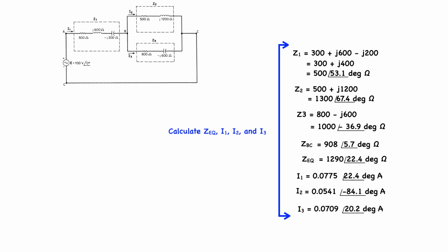Any reducible AC circuit, that is, any circuit that can be reduced to one equivalent impedance, ZEQ in this case, with a single power source, no matter how complex, can be solved in a similar manner to that which we have just described. The DC network theorems used in previous DC problems can be applied to AC networks, except that vector algebra must be used for the AC quantities.